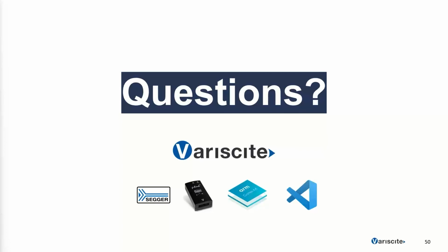Is there a preference in the Yocto version being used when performing this debugging environment, for stability and maturity for a product? Each of our Yocto release notes pages will have a row in the release notes that basically shows which Cortex-M features are supported. As far as I'm aware, all of the latest releases support the Cortex-M7 firmware. So if I were to recommend getting started right now, I would probably use the latest Yocto version from Variscite for the SOM that you're using.